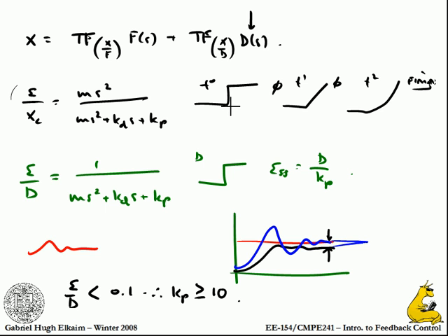However, if it's the disturbance that comes through, I actually get an error that is 1 over that, which has a steady state error to a single unit step in disturbance. So this is something to be aware of. This is why I don't like the terminology of what type a system is, because you have to be careful about what the input and what the output is. So this system is type 2 tracking a command input, but it's actually type 0 when trying to reject a disturbance.